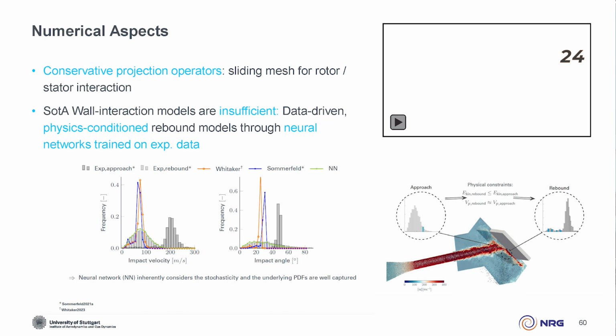And that is, well, you have these particles and they come into your engine. And the first thing they do is they hit a wall. They'll hit a wall, they'll exchange some energy, they'll bounce off the wall, they'll leave some erosion damage there, and they'll just keep bouncing and bouncing through those rotor and stator stages. They are all turning, of course, at an incredible speed, so this is a very dynamic system, and the particle's main interaction with the engine or with the geometry is through the wall interactions, when it hits the wall. Okay? So, what's the problem?